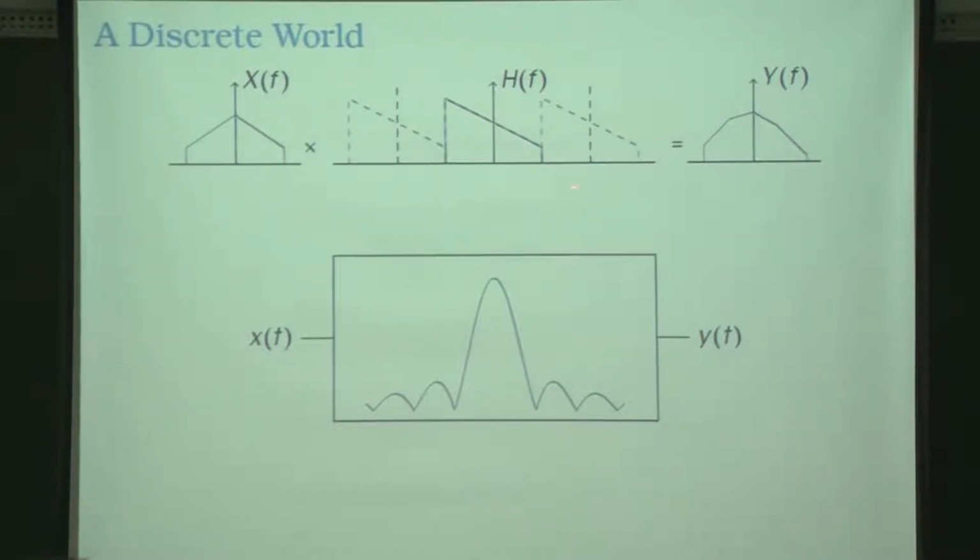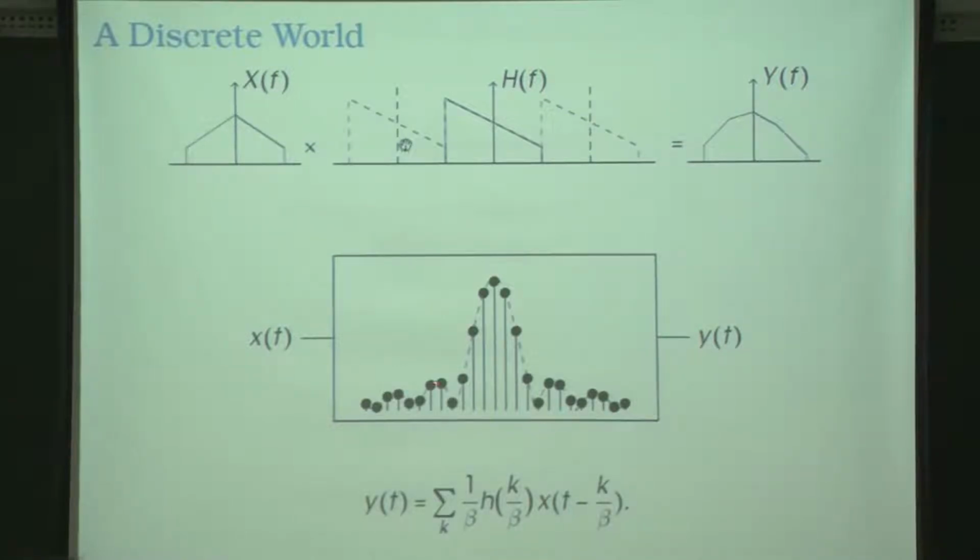So, if that is the case, why not repeat it completely through the entire axis? Then you get what is known as a periodic frequency domain representation. Then we can find the generalized Fourier inverse of this, because if you repeat in frequency, you just sample in time, right? So the same effect of a continuum system can be generated by a set of discrete impulses. The output is exactly equivalent to what is coming through the system.